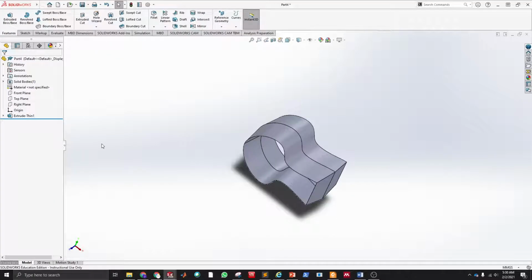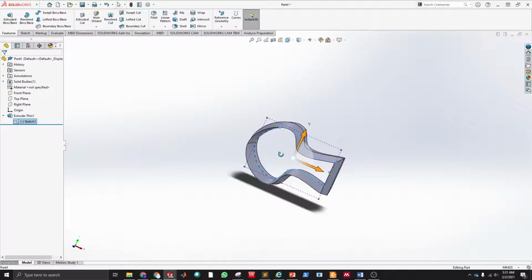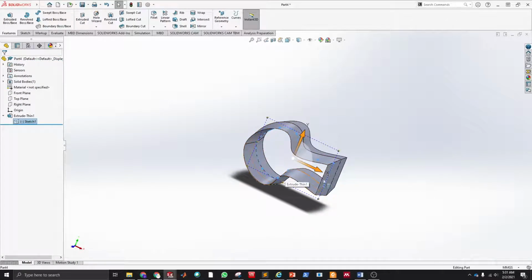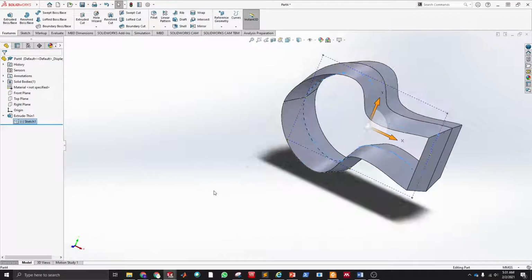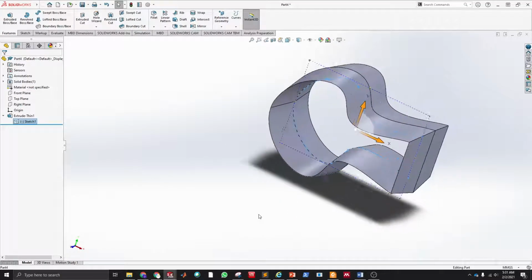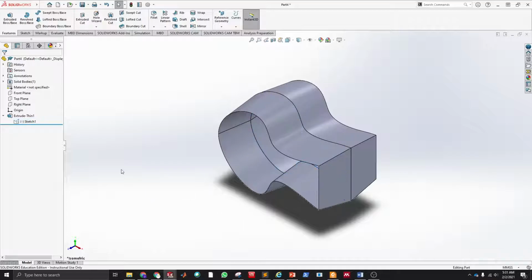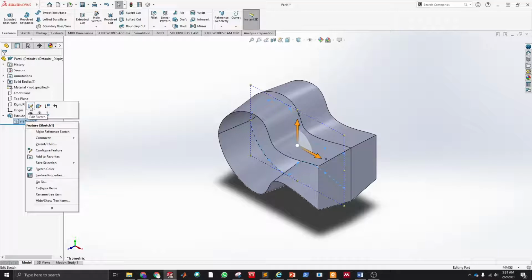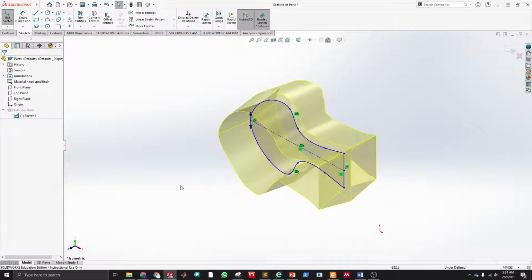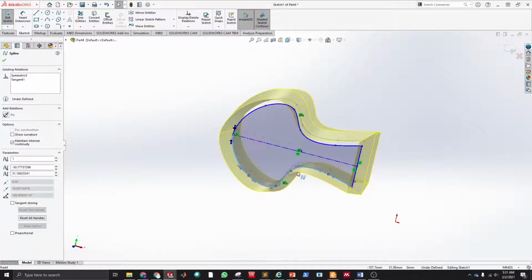So to edit an extrusion, as you see, the extrusion is listed here in the operations, but then it's related to one sketch, which is the line that I drew at the beginning. Control 7. And then if I need to modify that sketch, I can just deploy this arrow here and then click the sketch, right click, and the first option, edit sketch, and then I can modify this.